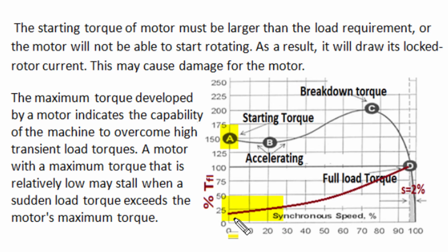of starting. If it is a normal fan or pump type of application where load on motor occurs only when motor gets speed up, so there is no need of very high starting torque, and standard NEMA B design ensures 1.5 times starting torque with rated voltage, and if you take a star delta starter and starting torque becomes 1/3 of normal voltage starting, then in that case starting torque is 50% of full load torque, and motor with that 50% of full load torque can accelerate and attain stable characteristic region.